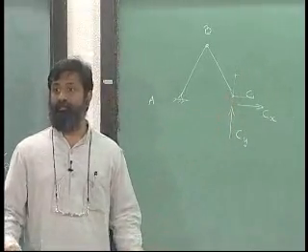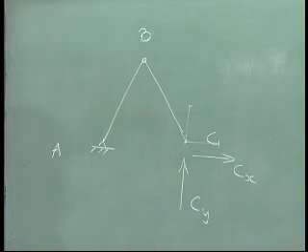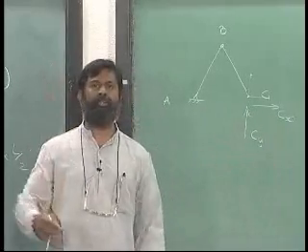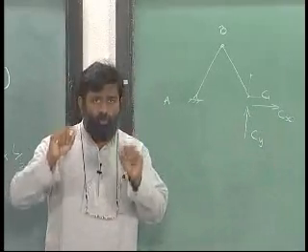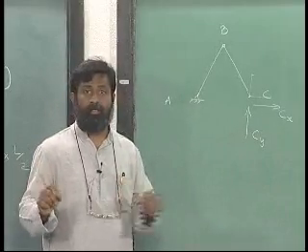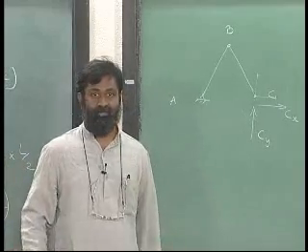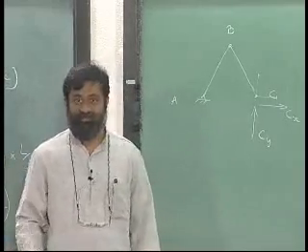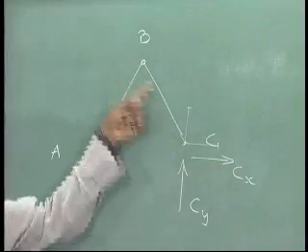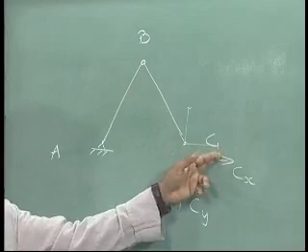Originally the degrees of freedom were 0. When I released one of them, degrees of freedom became 1. When I release 2, it has 2 degrees of freedom, which means I can specify two values, one independent of the other, as displacements at any single point. Is this point very clear? So in this particular body BC, I can specify a displacement in the x direction.